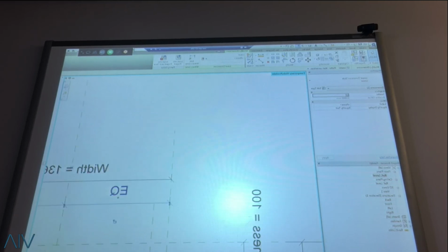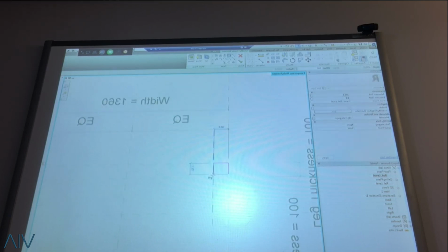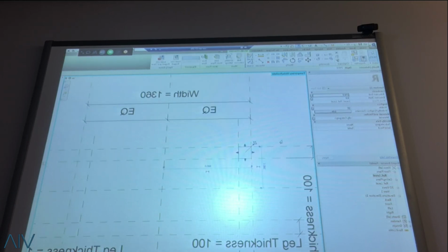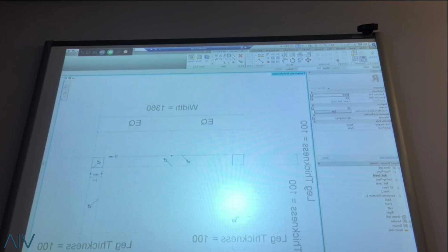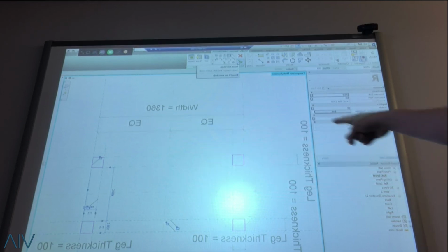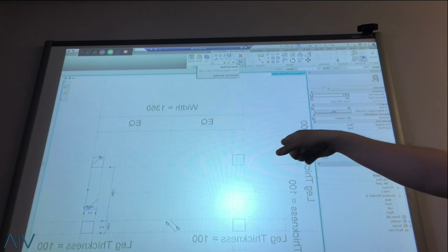Okay, in this particular case, I'm just going to draw it very quickly. So draw your rectangle. Okay, finish. Now I like to do it individually. You could do this. Okay, like that. Do you lock it to the reference plane? No, you don't have to. Because once you snap it to a reference plane, it just knows to lock. It's locked now. Okay. Now you could do this, but I would never do this. Do you know the reason why?